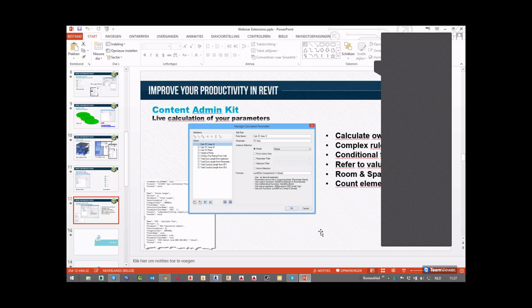So it's not only to check things, it's also to create rules, to map information, to tag that information in your Revit model. So you can create your own rules according to a local standard, for example, to calculate your airflow to your local standard and use that result back in your air terminals.